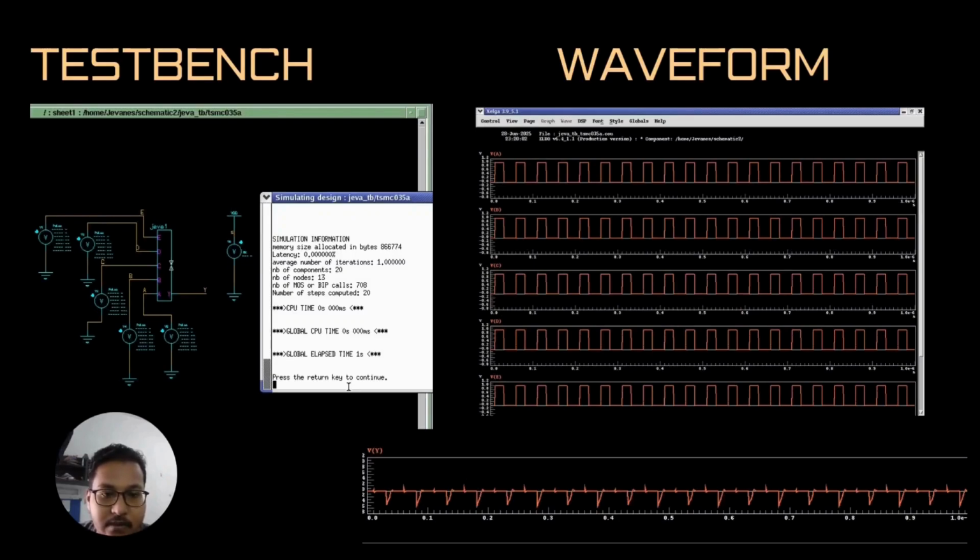The possible reason might be the probe declaration for each input and output. As we can see, the input seems like a correct pulse wave, but there is noise around it, and obviously the output looks not good, because the probe might be faulty.